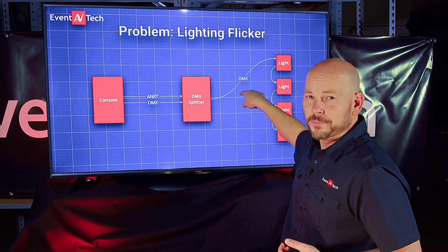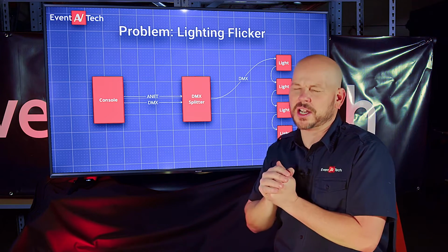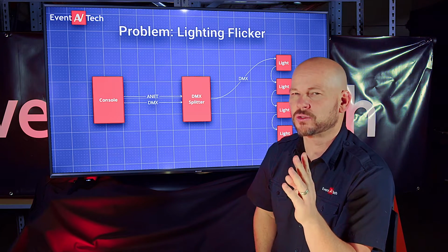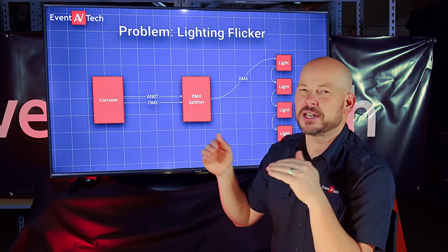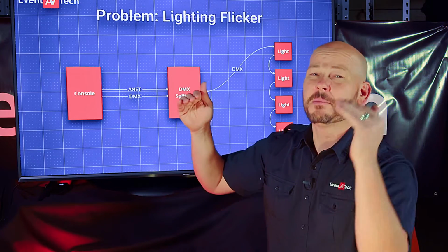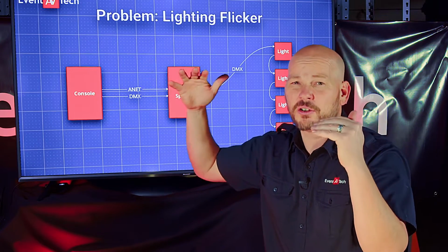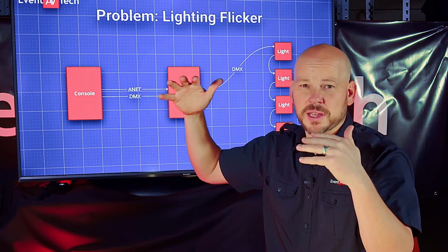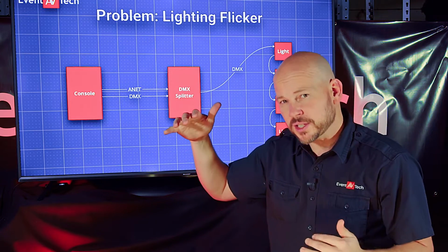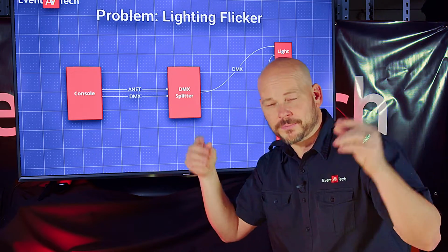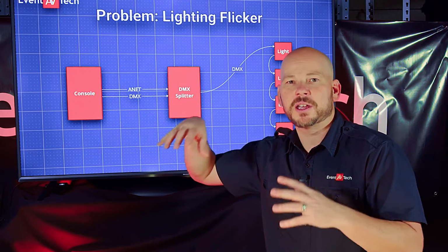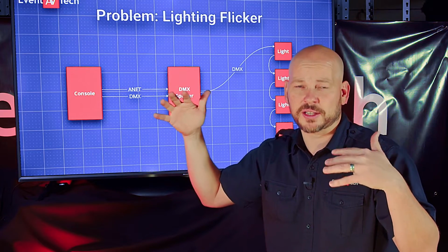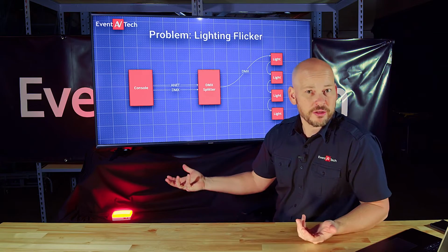The digital signal has to be within a range. I'm going to give a range, and if you're an engineer nerd out there, you might think I got my range wrong. This is a basic range, nobody's measuring, but the point is the impedance has to be between 75 and 130 ohms. When it drops below 75, it begins to flicker. Above 130, you might actually have communication problems, but that's the basic digital range that it's looking for.